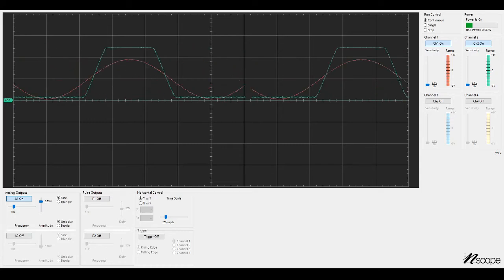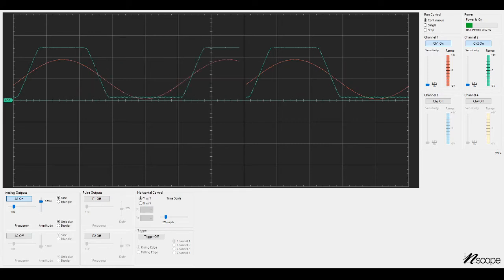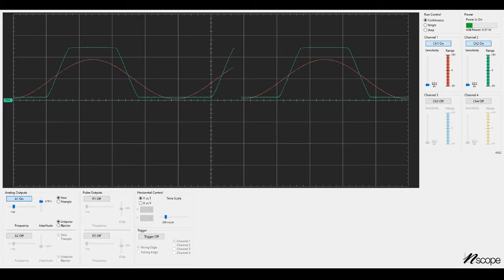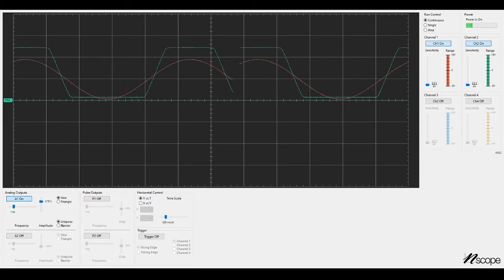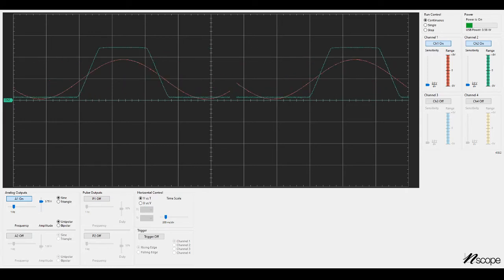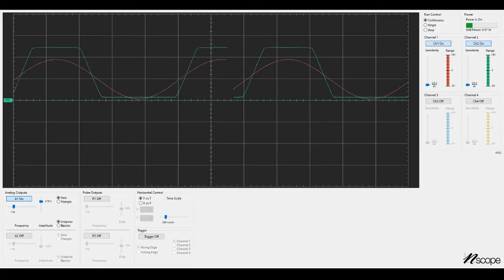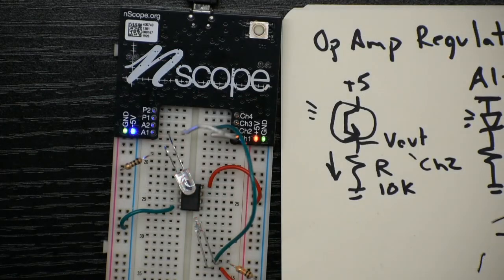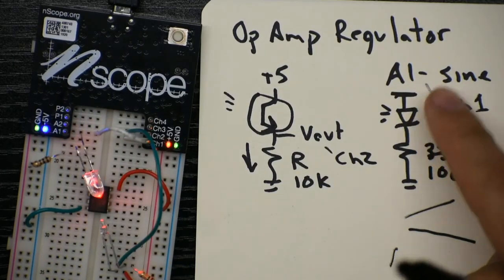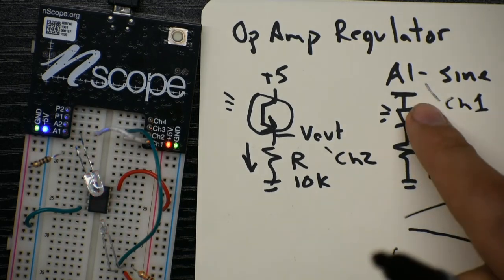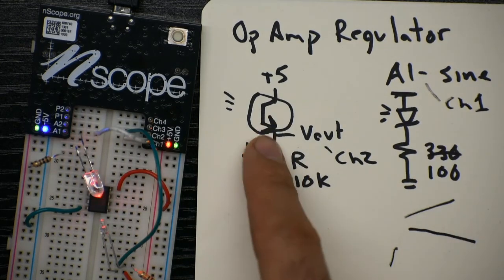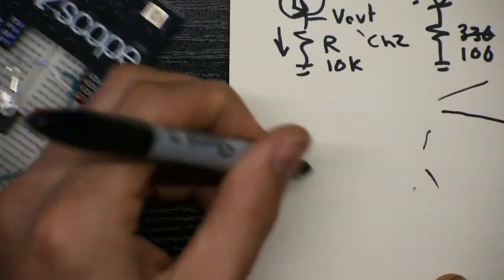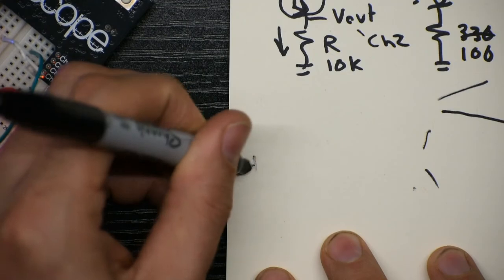So my goal is going to be to get a sine wave back out of my phototransistor, and regardless of if I stick my finger in the way or misalign the LED, I will always get that same sine wave back out, because instead of the sine wave going to my LED, I'll have the sine wave go to the op amp. The op amp controls the LED, and then the LED, of course, points at the phototransistor, which provides another input to the op amp.